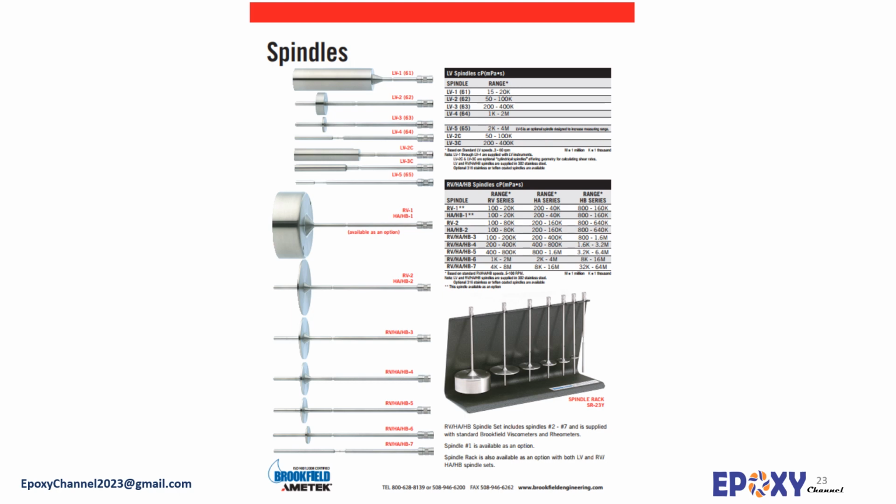Different spindle shapes and geometries have been shown in this figure. The spindle can be simply detached and another spindle can be used in the Brookfield instrument. Different types of spindles are suitable for different fluids with different viscosities. The higher the viscosity of a sample, the smaller the spindle. Details and properties of these spindles are provided by the manufacturer.